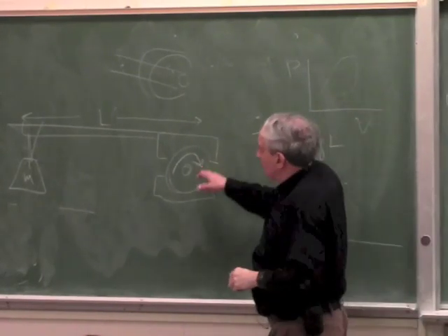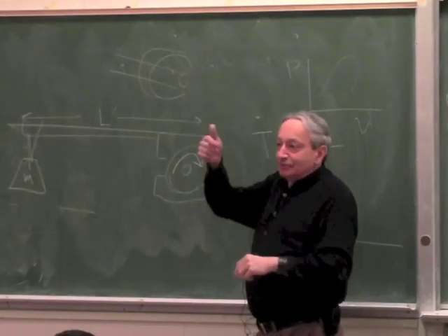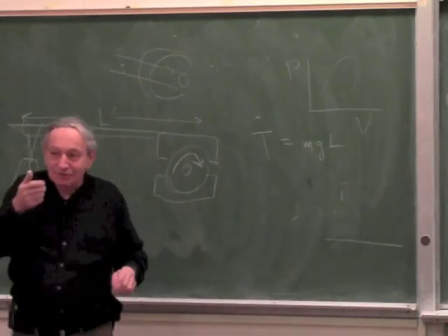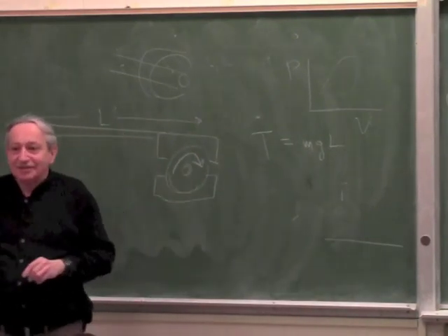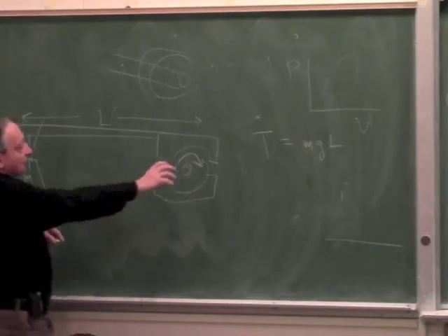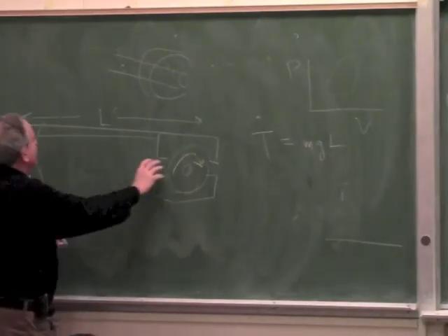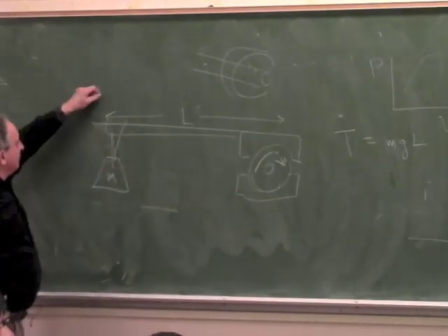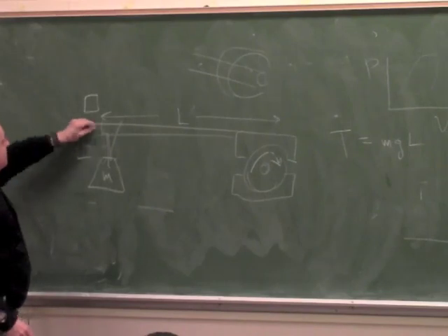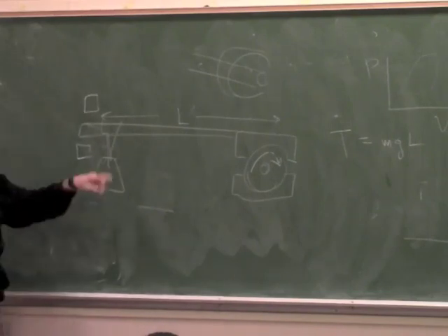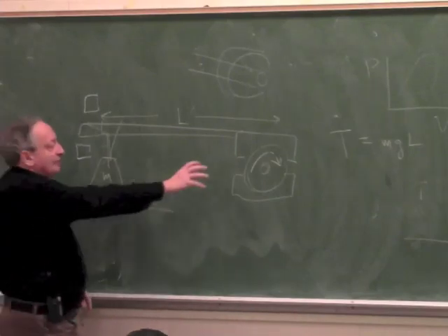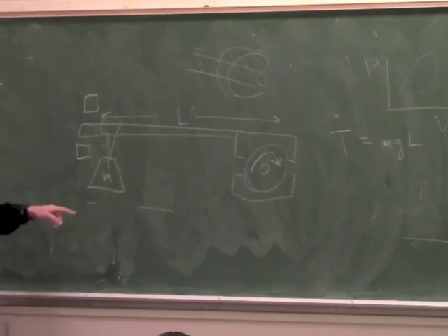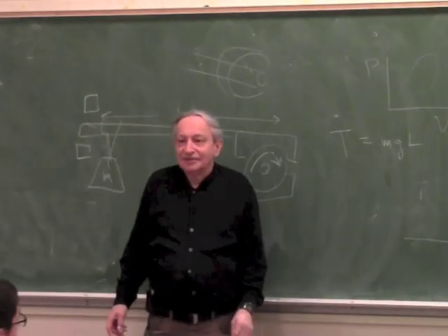So you knew the torque and you knew the speed. The speed you can just count, 1, 2, because this motor is very slow. The old engines were slow enough that you can just count by eye how many rotations per minute they did. So basically, if you wanted a different point, you clamped down the brake more, increased the weight more, until it slipped again. So this didn't move. You had a stop here and a stop here. So this arm had to stay between the stops. It didn't swing around. But you played around with the weight for a given friction until the arm stayed floating, and then you knew that that friction torque is mgl. Okay?